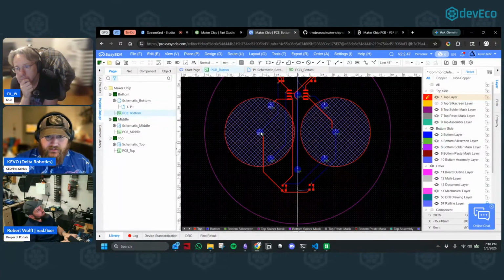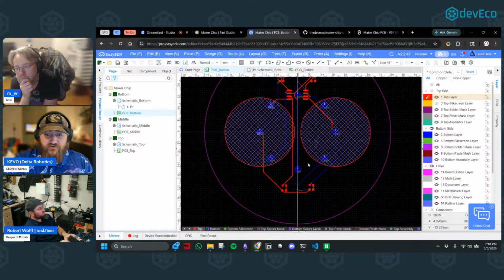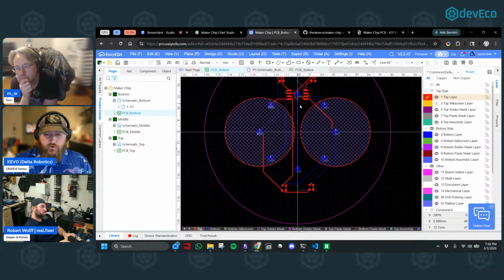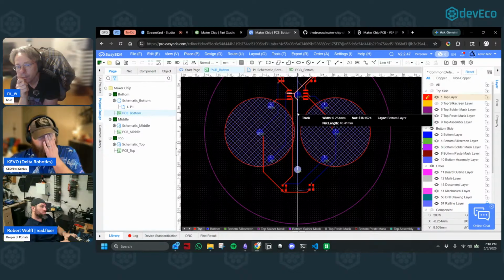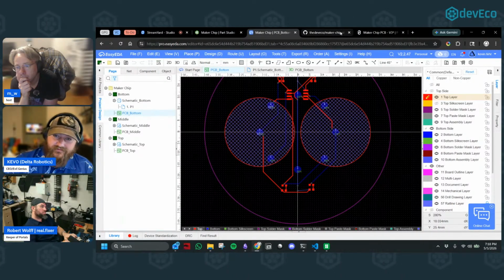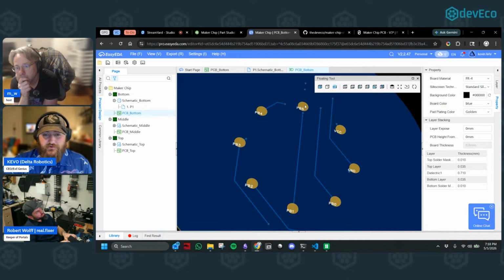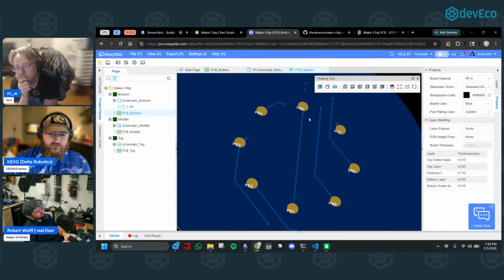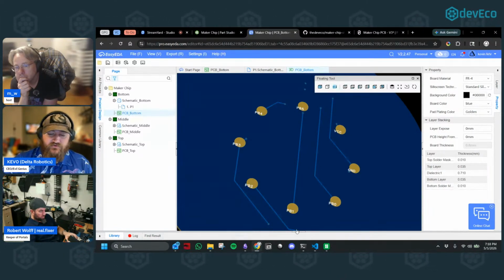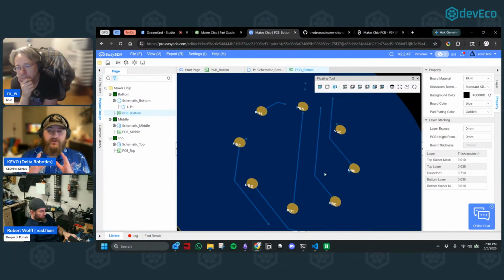So your magnet is perfectly positioned to provide even push pressure on the pogo pins here, so that you have good consistent contact. But just for compensation, they're oversized, so there's enough wiggle room for slight rotation, and even if there's uneven pressure on one side, it'll still make good contact with the amount of space that it compresses.